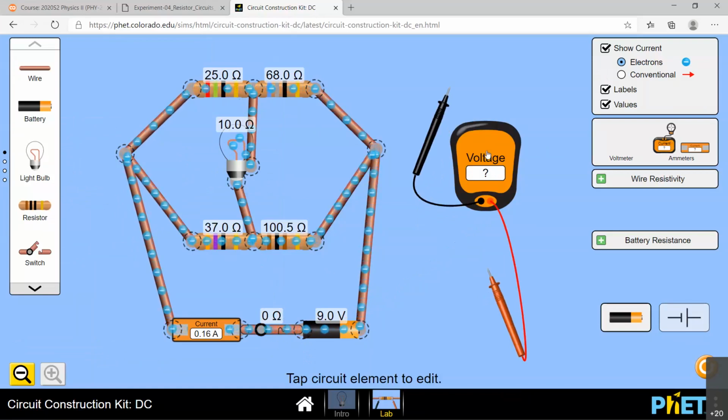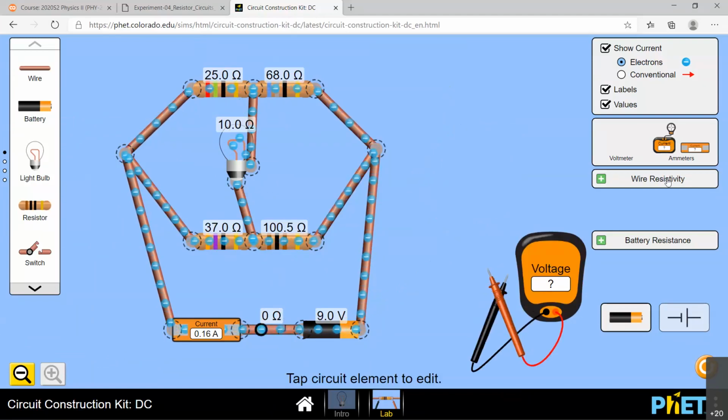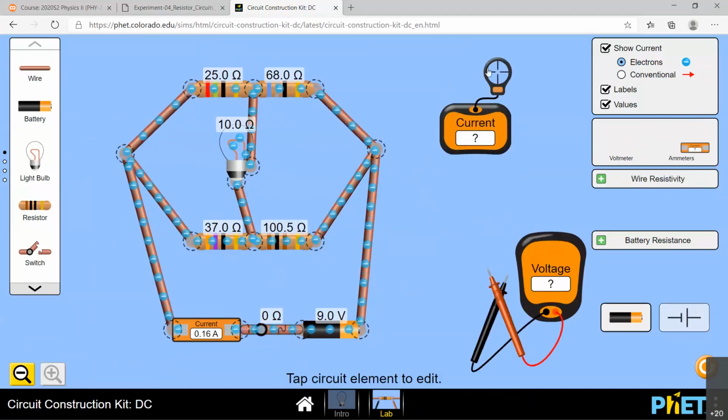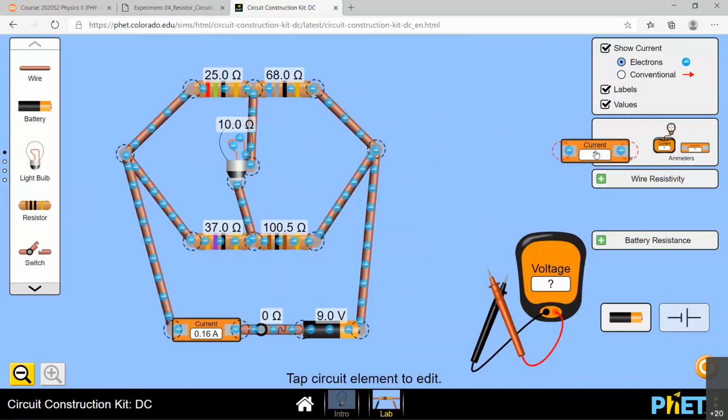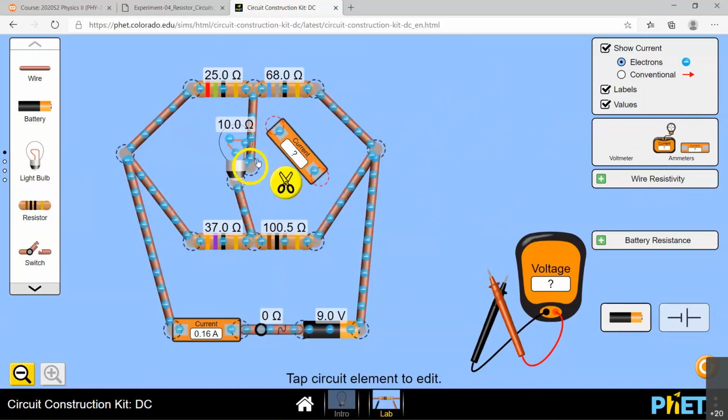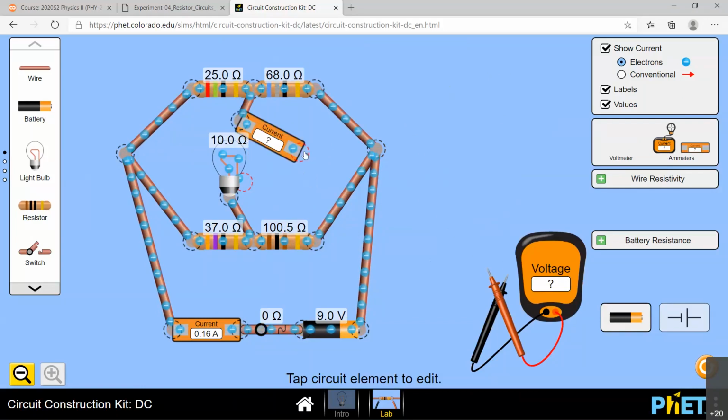Another way to measure this accurately is that you can either measure voltage or you can bring the current sensor and place it here to see whether the current passing through is 0, right? Either way is fine. Or you can put the ammeter directly across these 2 points. That also should work well. So I can put the ammeter across these 2 to make sure there's no current passing through here, okay? Let's disconnect this one and then connect the ammeter across that. There are various ways to adjust this, okay?